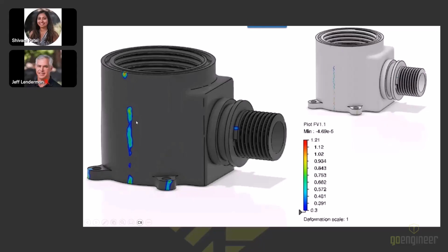As we look at that compared to the field variables, my higher numbers, my 1s and 1.2s, are in the areas of those low degrees, those zeros and 90s. The zeros, essentially, are where the worst numbers are in this field variable. And the better interactions, the 135 degrees, the 45 degrees, basically don't show up in the field variable plots. Okay? So that's part of the visual output I'm getting, but that's also why I'm using that scale of 0 to 1 as I was putting in my custom material properties.